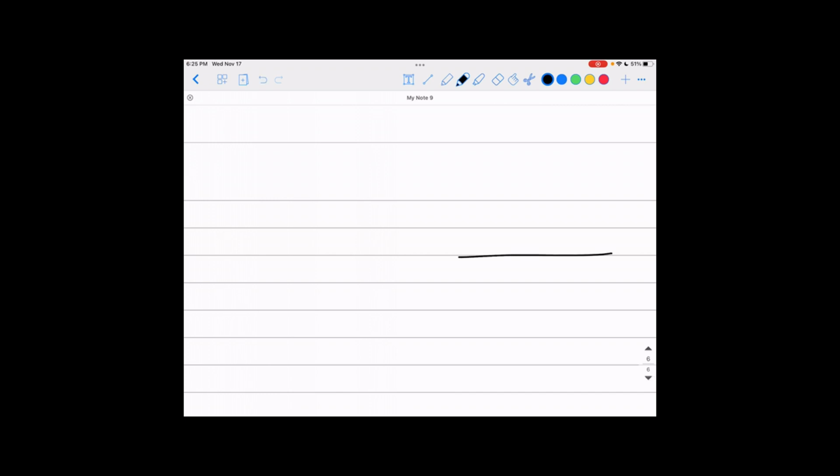Actually, you can keep increasing it. If you increase the rotor resistance much higher, you can even hit a torque-speed characteristic that looks like this. As you see in here, that is the pull-out torque here. It's the same as the starting torque, because that means this is all your stable region. You don't have an unstable region at all by increasing the resistance that high. Okay, so problem solved. Increase the rotor resistance as much as you can, and now you have a very wide stable region and don't even have any unstable region.